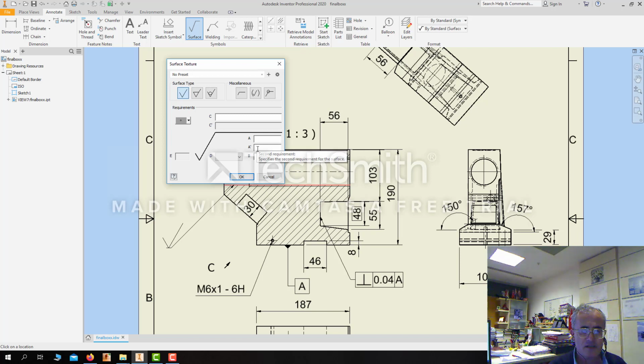The other box is where the cutoff value may be written. One of them is roughness height, and the preceding abbreviation in the new format is a must. It is not optional. Say RA, arithmetical average of roughness height, and it is 12. Into the second box, write the roughness cutoff value. Say that it is 0.8 millimeters.